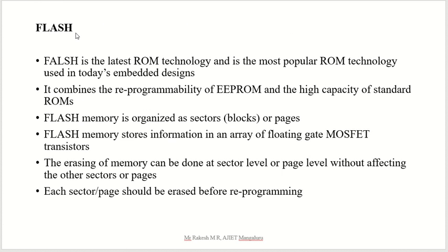Then flash ROM. Flash is the latest ROM technology and is the most popular ROM technology used today in embedded design. We are using it till today also. It combines the reprogrammability of EEPROM and the high capacity of standard ROM. Flash memory is organized as sectors or pages. This is the advantage.